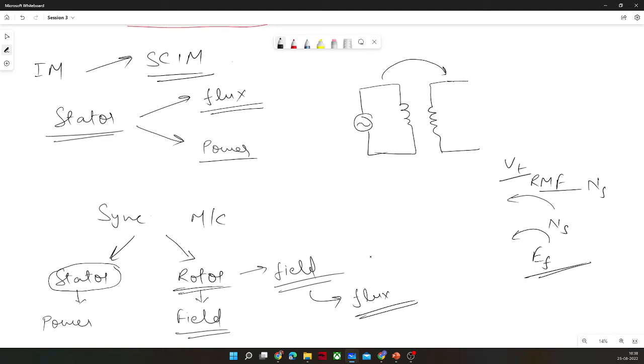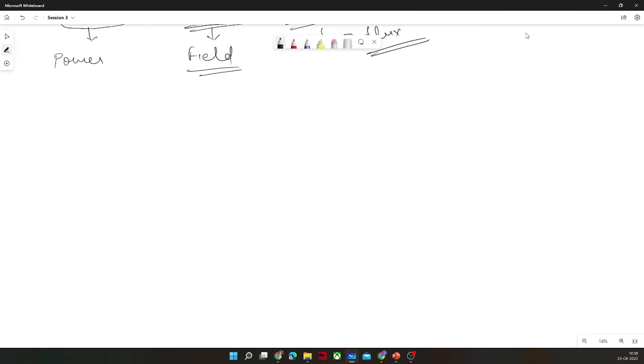So to make any torque, let's say this is the field component and this is the armature component. To produce torque in any machine, torque is directly proportional to FF and FA and the sine of the angle between them. So if both are orthogonal, we are trying, with the help of slip rings or brushes, to maintain both components orthogonal so that we can achieve maximum torque.